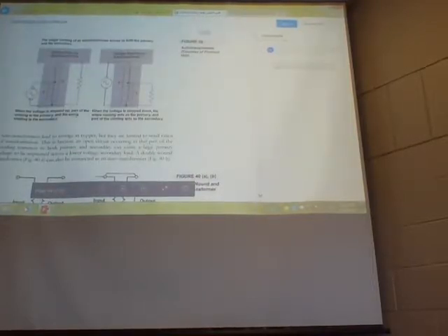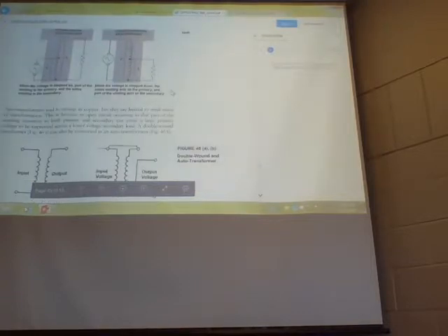So when the voltage is stepped up, part of the winding is the primary and the entire winding is the secondary. This is your voltage applied to it, that's your primary. You're stepping up the voltage, so this many turns is used for the primary, and all of those turns are used for the secondary. If it's a step down transformer, your applied voltage is connected to all of those turns, and the secondary is connected to a smaller number, giving you a lower voltage.